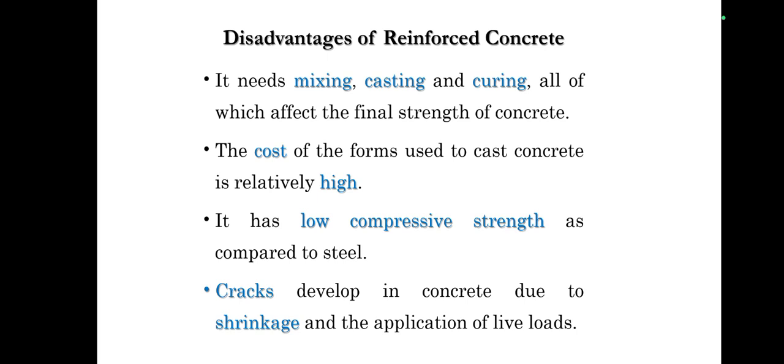So if deflections or deformations are becoming more, then it might lead to crack formations. You can also say the cracks can be developed because of shrinkage. What is meant by shrinkage? Shrinkage is the volume changes occurring in the concrete. Because of that also there might be crack development.